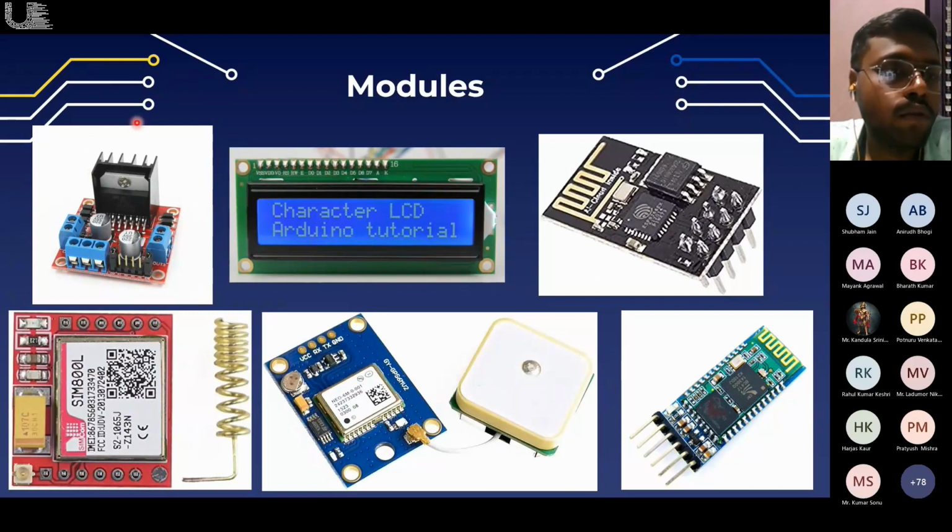This motor driver module we use to connect stepper motor or any normal type of motor with the Arduino board. For example, if after receiving some input and processing on it, you want to do some actions like rotating a wheel, for example, if you use obstacle detection using the infrared sensor, and after that input taken, you want to rotate the wheel or turn the drone or turn the cart in other direction, so you can use this motor driver module that will drive the wheels in the particular direction.